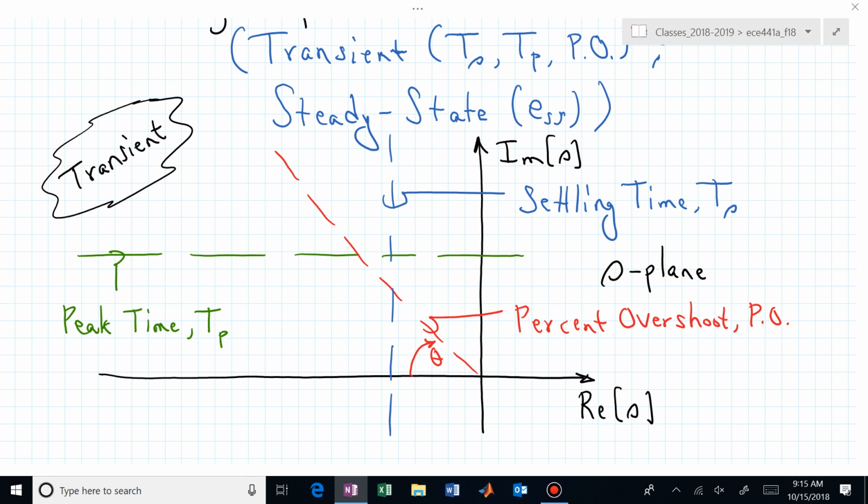And so that means you probably are wanting to squeeze or pinch those poles into a smaller wedge if you now have finite zeros that are in the same general area as your dominant poles. Those zeros dramatically change your percent overshoot characteristics. Just saying. But for now, for this exam, you're focused on a pure two-pole system which says just poles, no zeros. Is that clear?